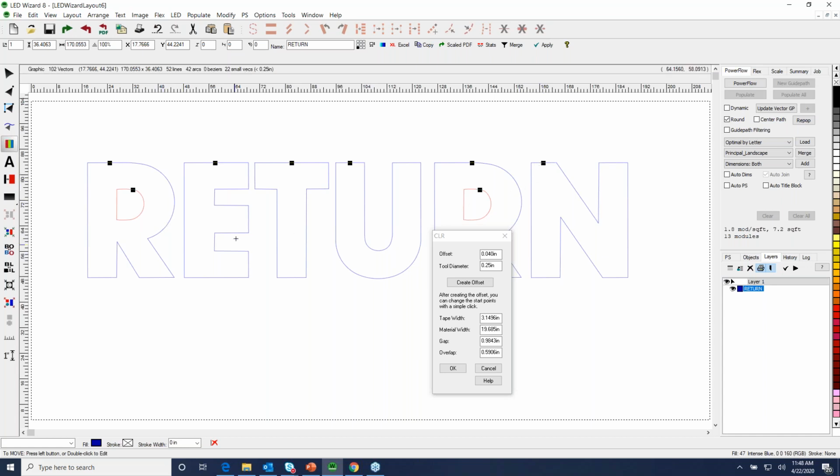Now, I like them on the top. I like them on a straight line if possible. You can put them on a corner. You can put them anywhere. Internals, maybe you'd have some other way to do those. You certainly need to make sure that you have the correct loop directions because these are directional, outside clockwise, inside counterclockwise. Okay, so on the R, our pattern starts here, goes this way, and goes around that arc first.